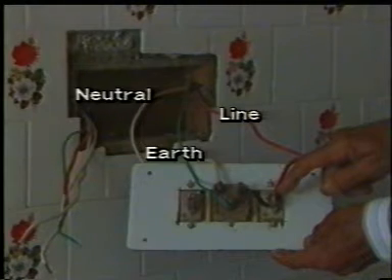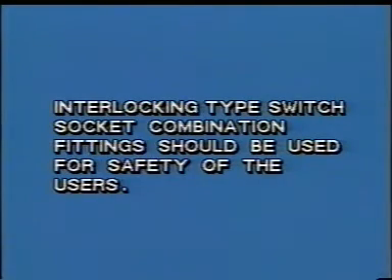Phase wire must be connected to control switch and proper color code should be followed. Interlocking type switch socket combination fittings should be used for safety of the users.